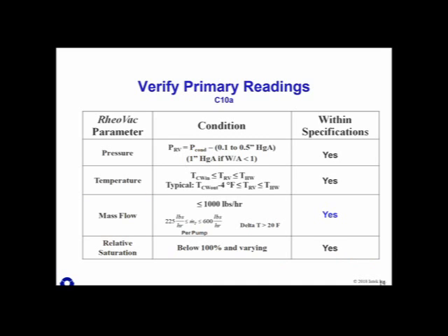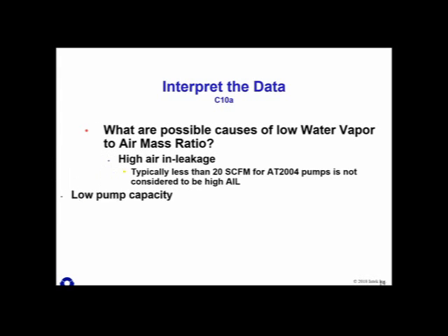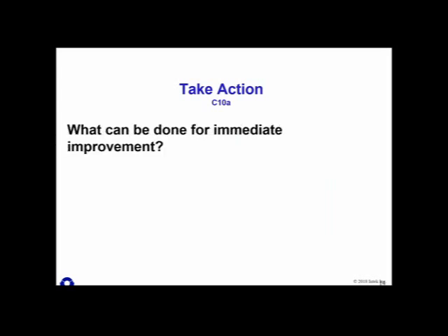So now we'll handle a case study where I think we went through this. I'm going to blaze through some of these because we're kind of short on time. Anyway, all three of these are operating low. They could reduce condenser pressure by running all three. If they don't want to, they should be looking at maintenance. If all three are low, I would recommend looking at the heat exchangers. If all three of them are low, the heat exchangers have not been maintained, or maybe the seal water overflow has not been maintained. They're running dry. One of those two issues is most likely the problem, something that's affecting all of them. So that would be an issue.